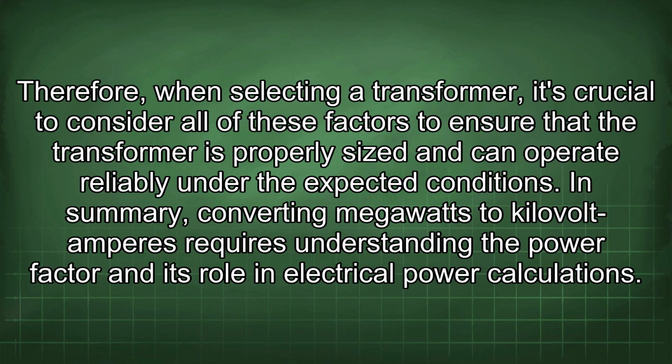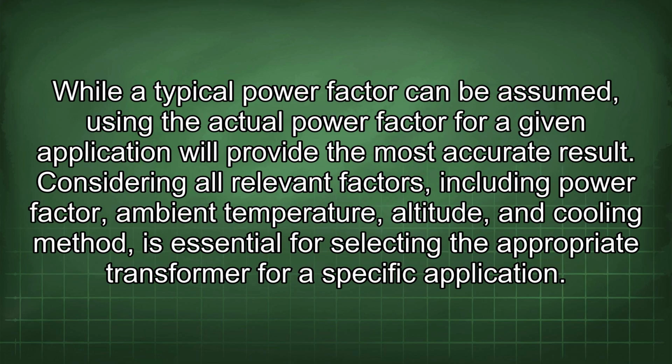Therefore, when selecting a transformer, it's crucial to consider all of these factors to ensure that the transformer is properly sized and can operate reliably under the expected conditions. In summary, converting megawatts to kilovolt-amperes requires understanding the power factor and its role in electrical power calculations. While a typical power factor can be assumed, using the actual power factor for a given application will provide the most accurate result. Considering all relevant factors, including power factor, ambient temperature, altitude, and cooling method, is essential for selecting the appropriate transformer for a specific application.